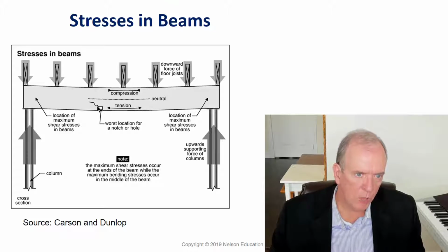It's also why you can't notch. They don't even allow you in the building code to drill through a built-up wood beam. So you have to be careful of notching and drilling requirements. I'll cover that in the lecture that we do on the subtrades. They tend to like to drill through things.